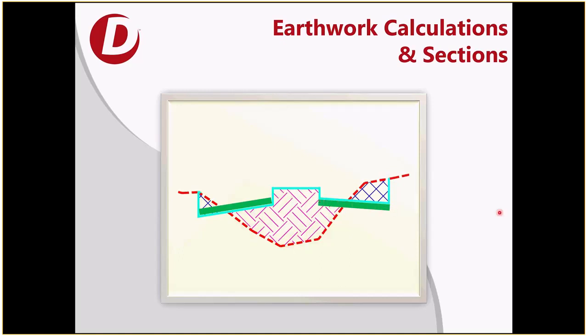So when you're working with existing materials, for example, in a lime-treated subgrade, you want to count the subgrade above that line. When you're working with imported materials, you want to count the line below that line. And I've seen mistakes on earthwork models happen in both directions, where someone just looked at the structural section and made an assumption about what needed to be included in earthwork, and it wasn't correct. So keep an eye on that when you're building your model with respect to what actually defines the typical section.